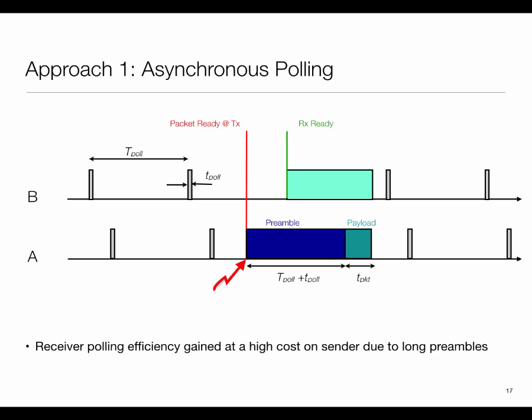So in this particular case, I need frequency synchronization. Both parties need to have the same frequency, but I don't need time synchronization. I'm achieving time synchronization by virtue of sending this long packet out.